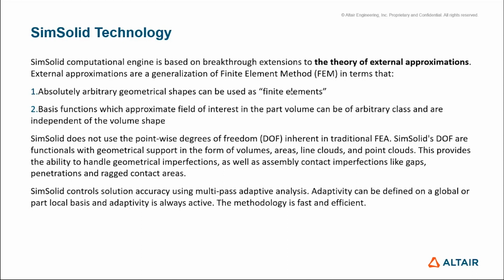Single parts as well as multiple assemblies can be imported into SimSolid. Each of those parts is defined as an element. So no matter what the shape of that part is, it is an element. Important to note, SimSolid only works with volumes. Very important to note. Whether they're thick or thin, that's not the problem, but you can't import a 2D surface that does not have any thickness or any curves. It will ignore that type of geometry. So it only works with solid geometry.